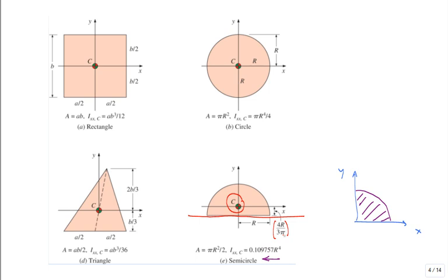If we had time, I'd get out the old calculus and do the integral and prove it, but I'll trust it. Okay? Well, for this case, how much do I shift over if I do a quarter circle? I know how much I shift up if I do a half a circle, but how much do I shift over? Because I really want to find that location. Yeah, the same. The professor never told me exactly the same. Well, symmetry and logic says it's going to be the same. Okay? So it's going to be shifted over as well as shifted up by the magnitude 4r over 3 pi.